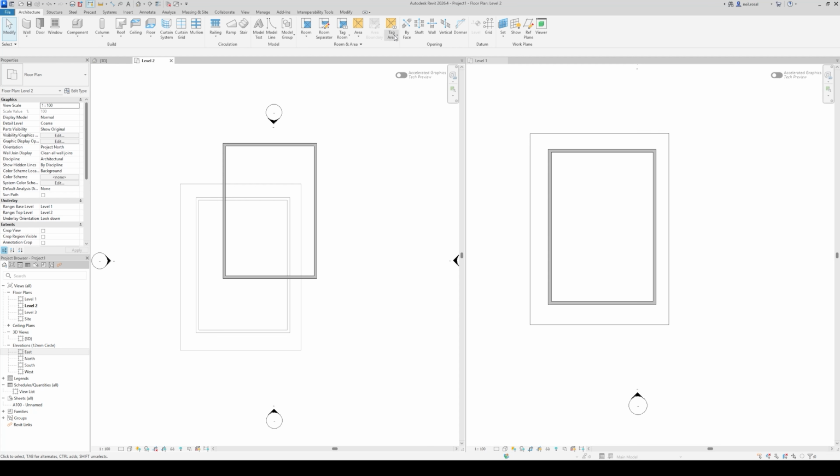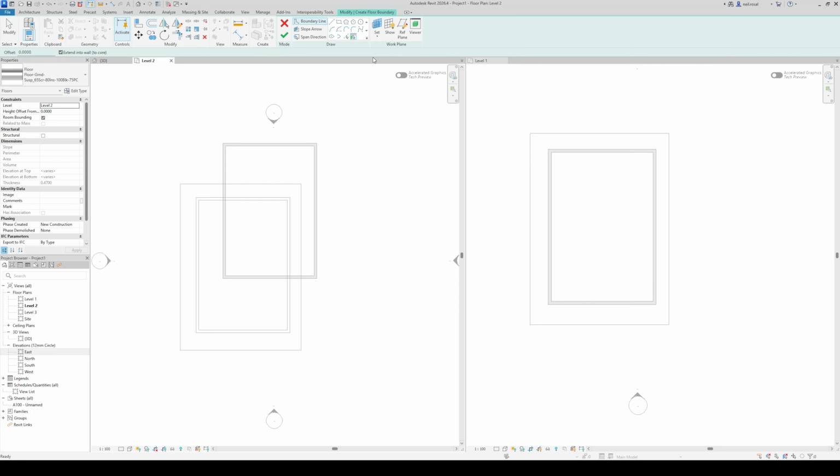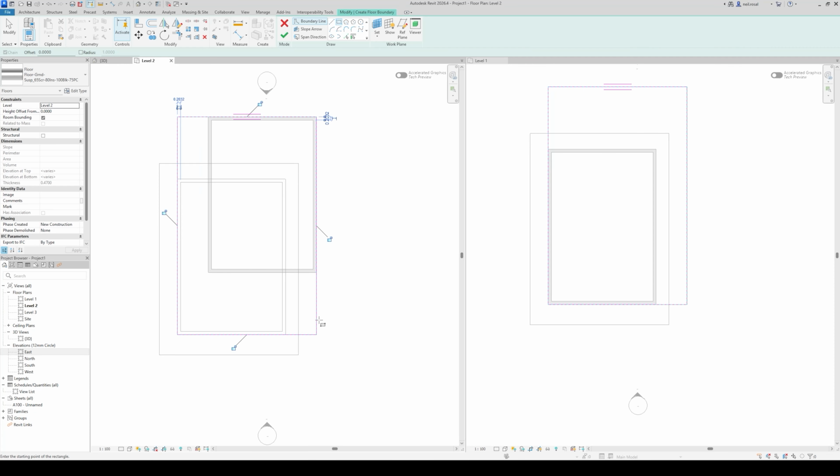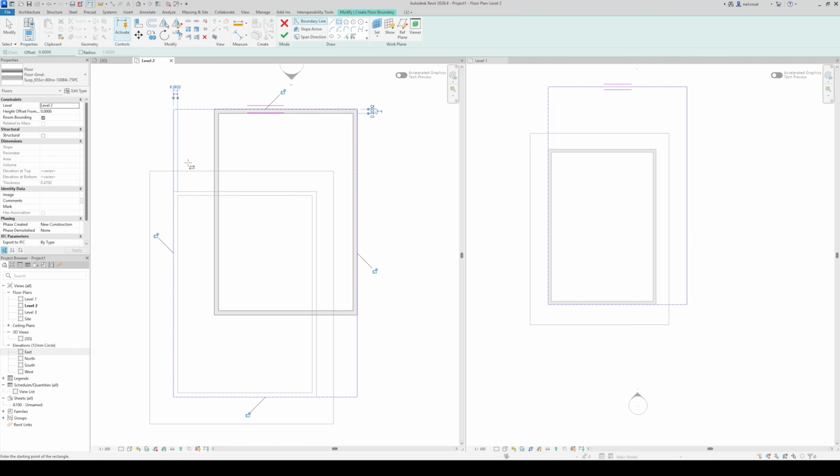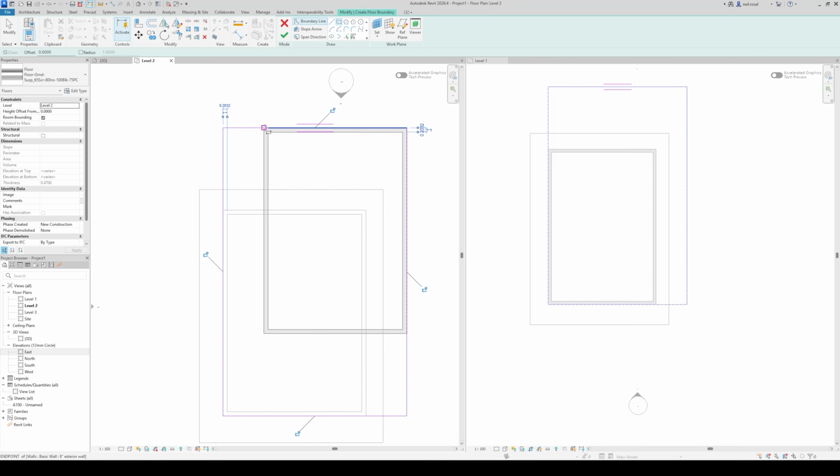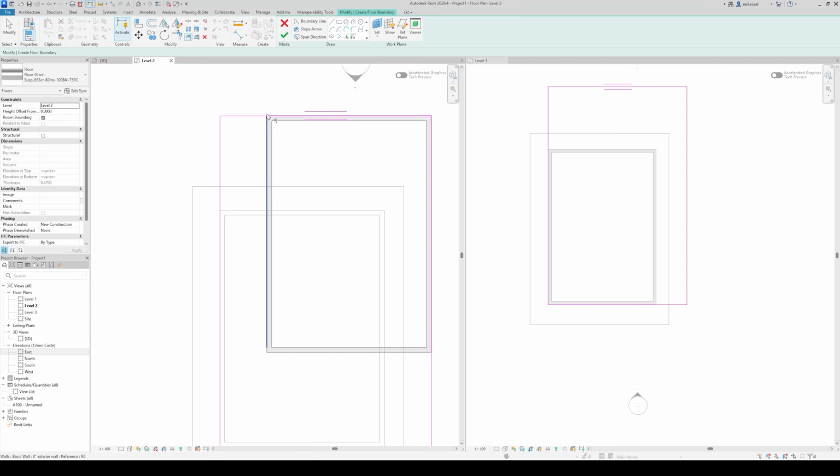So we're still going to create a rectangle using the floor boundary edit boundary tool. I'm going to select that corner to this corner, and I don't want this space here. Actually, maybe I don't want this space right over here. I'm actually going to keep this space. Maybe that's like a balcony that I want to have in a later tutorial, but I don't want this space over here. So what I did earlier was use the trim tool, and we're going to use that trim tool as well to get rid of this space.